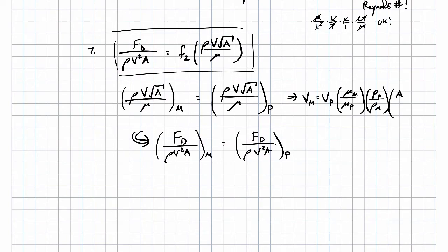And then we have the square root of the, well, I'll just write it as the area of the prototype over the area of the model, and then take the square root of it. All I've done is rearrange my Reynolds number. Well, if we're using the same air in the model and the prototype, then these will just be equal to 1. Okay? And we're told that the model is a 1/4 scale model compared to the prototype.